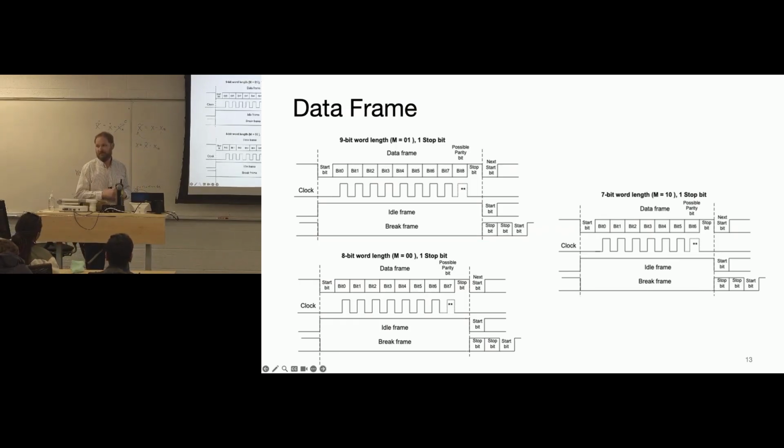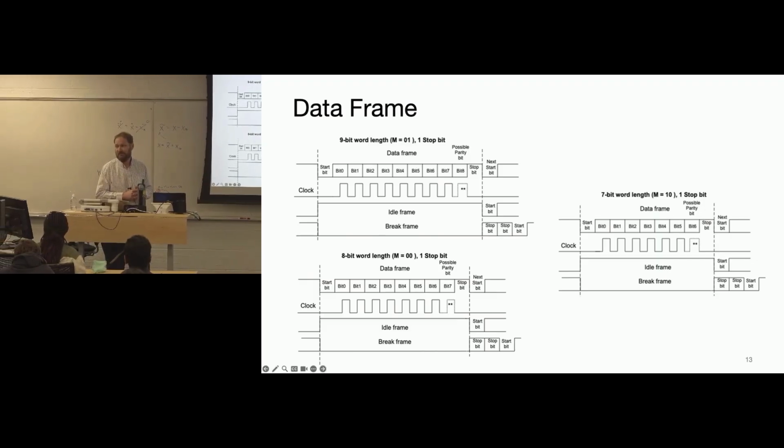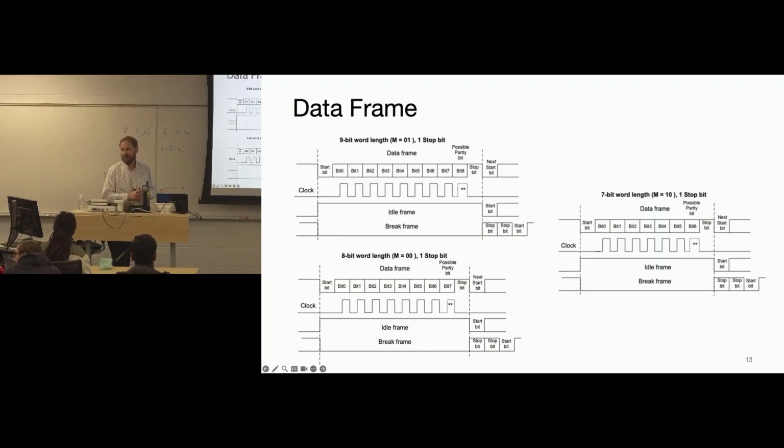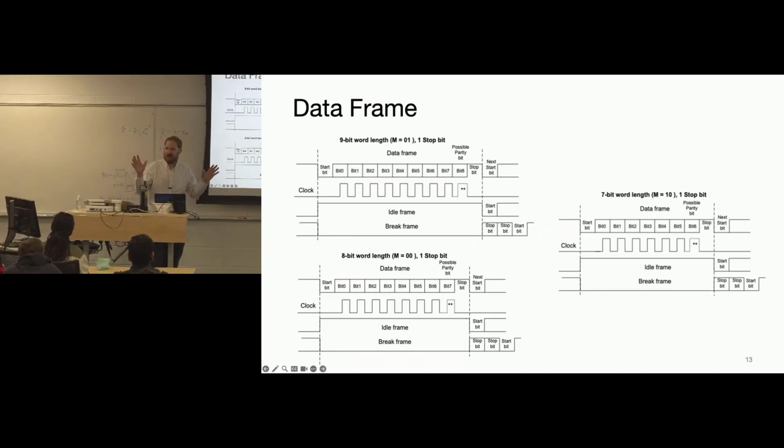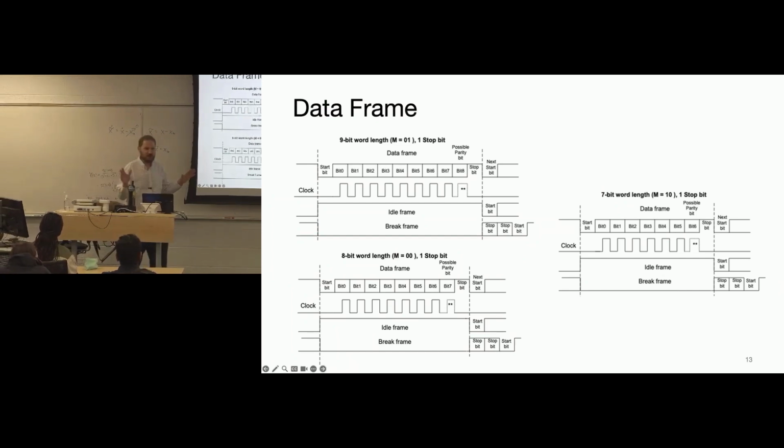So if you have a device that uses serial communication, and you're using a microcontroller, would the device have within its data sheet a baud rate, and then you would set your microcontroller to that baud rate? Yep. That's the first layer of problems when we work with UART.